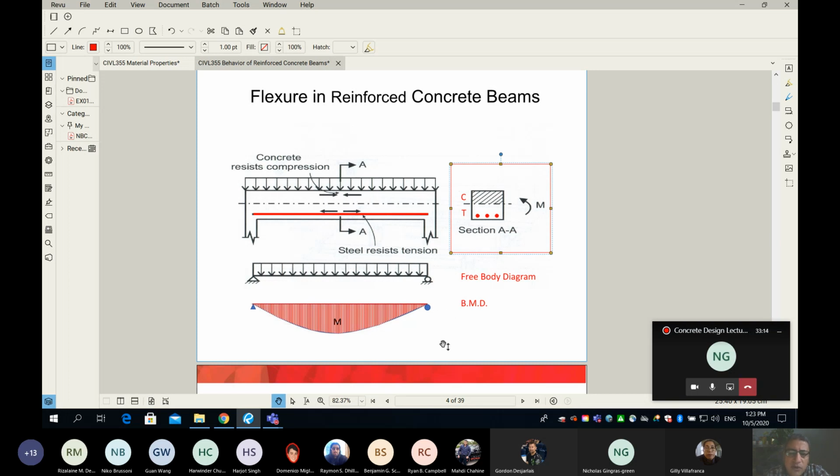And as I said before, the way I draw the bending moment, to be honest, is the best fit for this class. Because if you simply draw the bending moment the way I do on my screen, right away you know that you have to put your reinforcement at the bottom side of your beam. Okay, and look at the cross section. Yes, we have 3 bars here in red because this is the tension side of your beam.